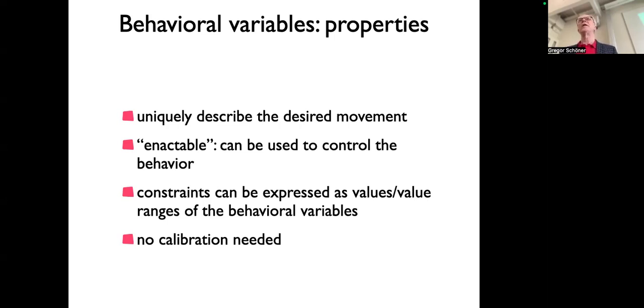And so when there is any kind of slip, and for actual cars on the road with uneven ground, that's a real issue. And that is then a control problem, how you do that optimally, especially going around bends, and there are complications. These robots are ideal because their rolling condition isn't violated, as you might know, for actual vehicles with more complicated geometries. The rolling condition is violated, so there's some friction, and the wheels always slip a little bit, and so on. And so that's what the control guys work on, how to do that optimally and so on.